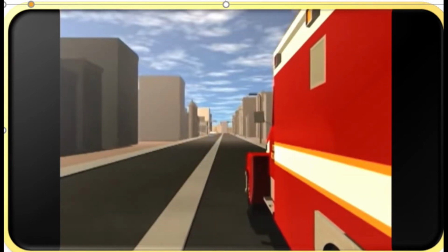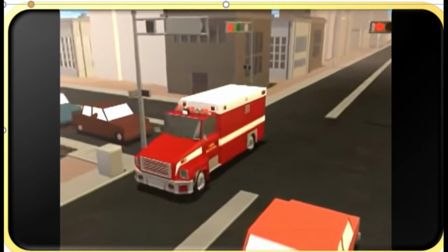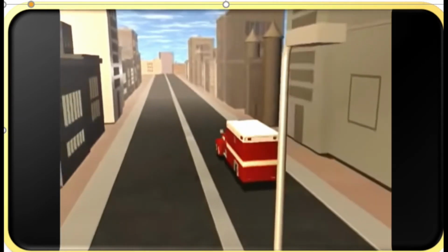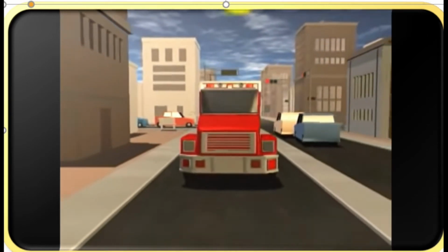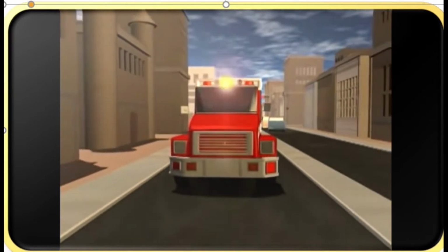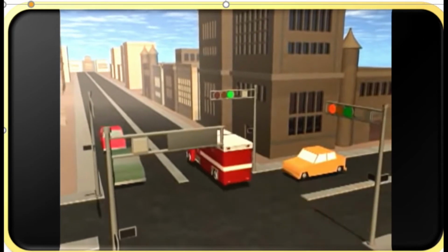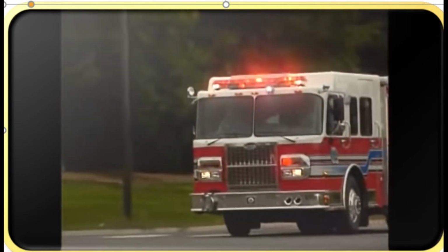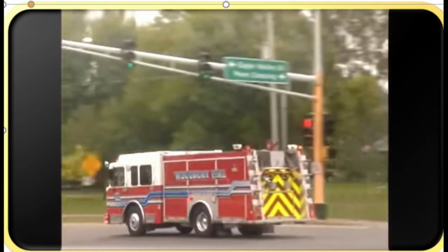The Opticom infrared system is designed to initiate signal changes that seem normal to other traffic at affected intersections, reducing confusion. The infrared emitter is a forward-only transmitter, so the Opticom infrared system does not affect parallel streets. Proper programming of the signal controller timing minimizes disruption to cross-traffic. The goal is smooth, rapid advance of the emergency vehicle through intersections, getting responders to the scene more safely and in the shortest time possible.